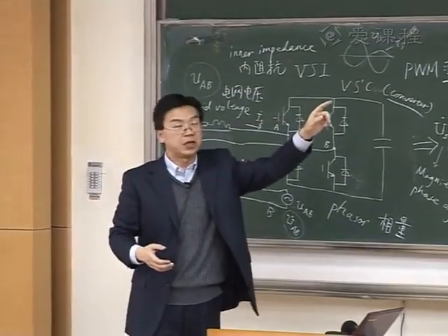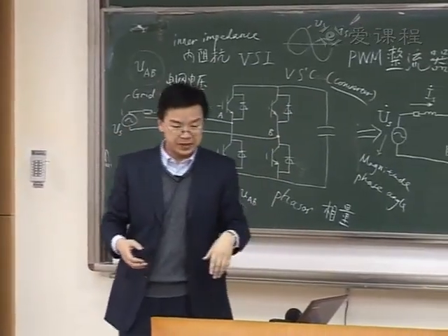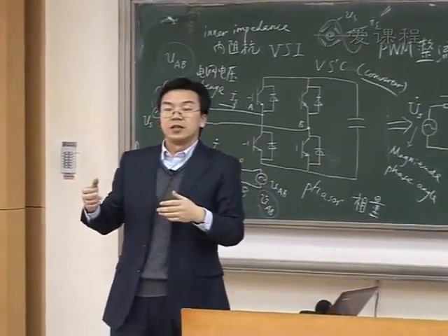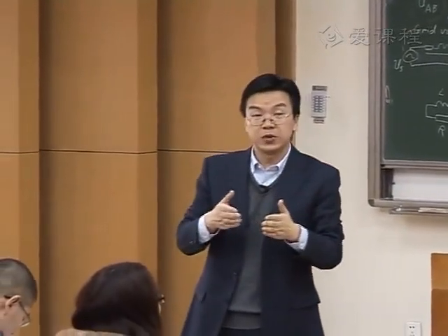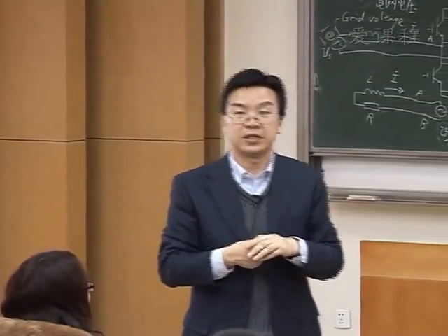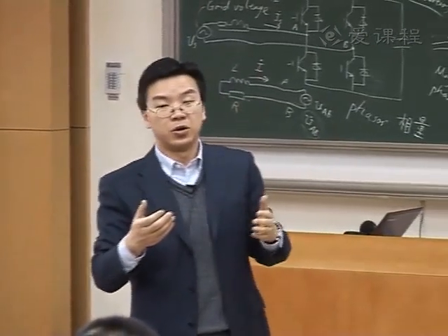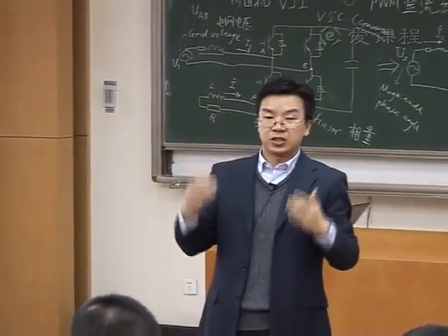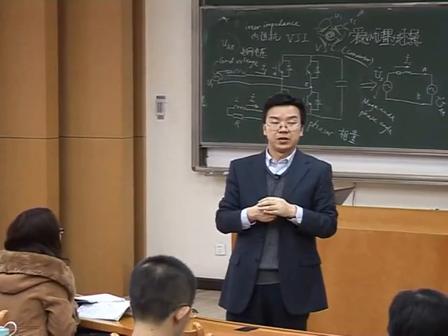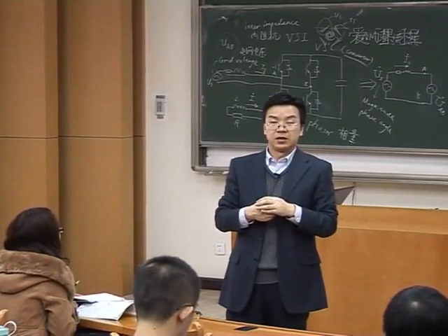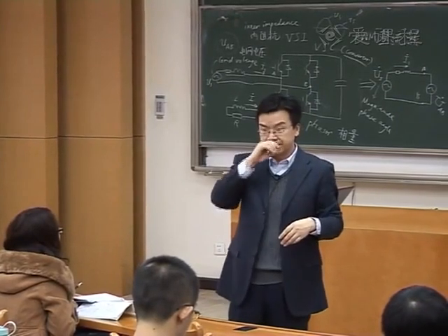And therefore, that means what? That means the phase angle of the current can be controlled not exactly 90 degrees leading, but with a certain angle difference, not exactly 90 degrees. And therefore, we are absorbing not just reactive power, but also a little bit of active power. But that's in the practical case. You are right.